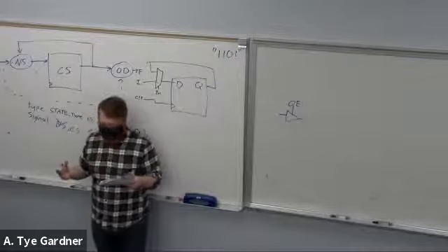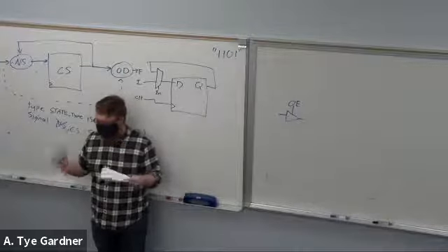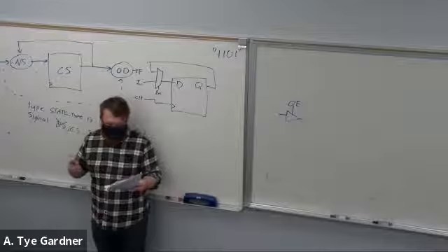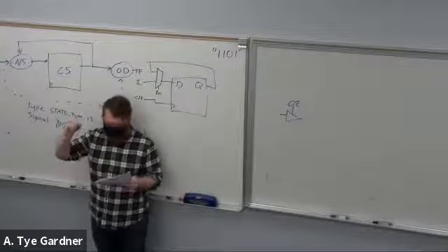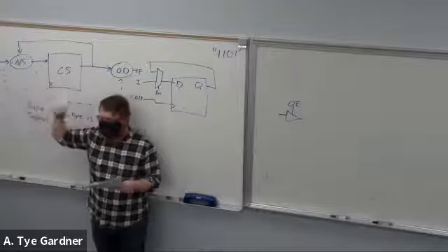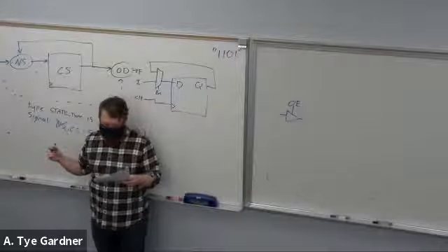instantiations instead. And then I wanted to make sure that you remembered if I'm doing a variable bit, you use the generic map. I didn't care if you wrote a value there or not, as long as you had the n colon integer or n colon standard logic, right? Something that showed me that you had that generic map, and understood that's where you were going, what you would need.